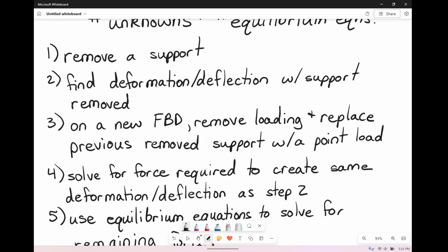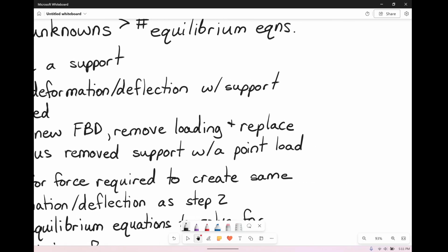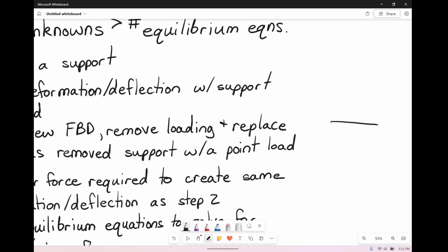had from before. Because if you think about it, all that's really going on in a statically indeterminate system is that you put an additional brace to prevent motion. So, for instance, you had a support, you had an additional roller, and you really didn't need it. And the whole reason you put it here is so that the deflection at this point was 0.